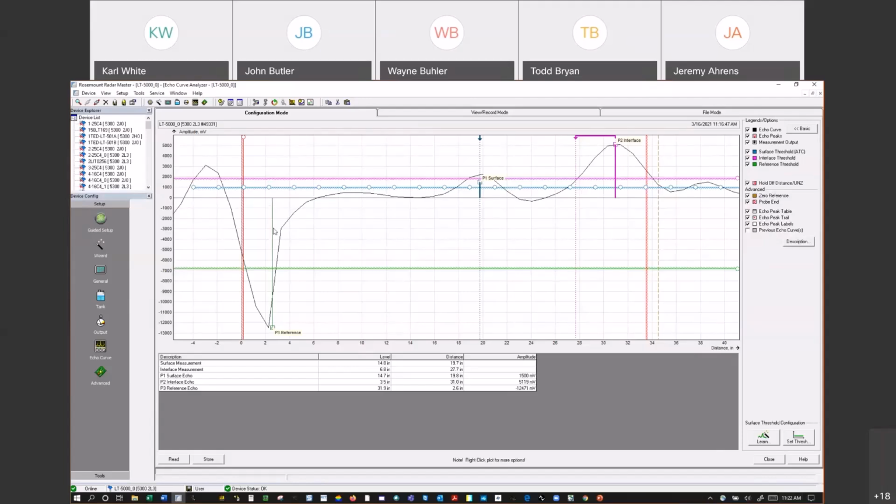If everything's right on the radar, it's configured properly, you can look at that distance to the peak, and it's usually spot on. It doesn't give you false readings normally. Where a float or anything that works off density, it's always calibrated to a specific density. If the density's off, it's going to be off. There's nothing you can do about that. So I'm going to second or third that opinion on accuracy of a radar.